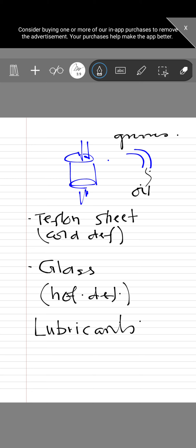So with this reduction of friction, or attempted reduction of friction, a strain of 1.0 can be achieved without the barreling effect. So up to this strain, the barreling effect can be prevented.